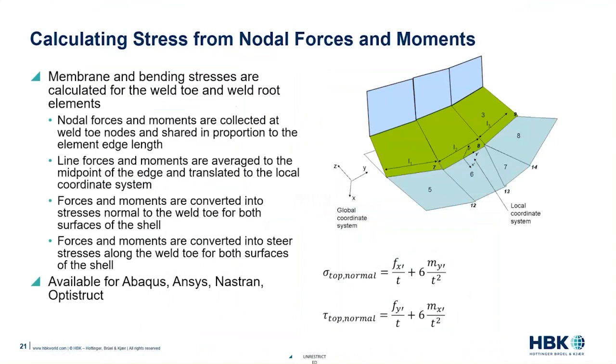So this previously recorded webinar describes how the structural stress method is used with a simplified finite element modeling approach to calculate forces and moments at the weld toe or the weld root.